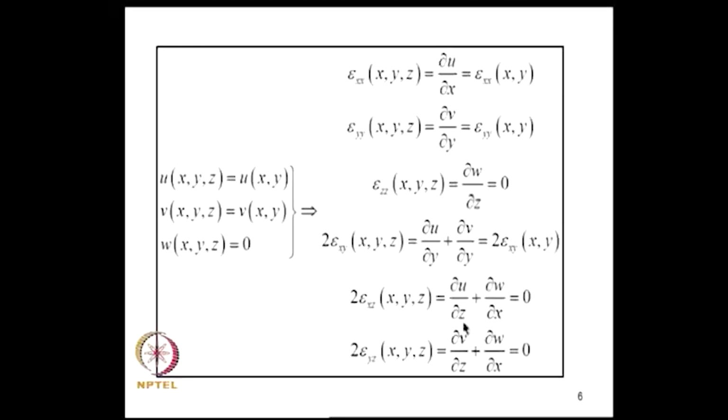So, this is the basic plane strain model, postulates of plane strain model. As you see here, the postulates are on displacements, whereas in plane stress model the postulates were on stresses. Now, starting with these displacements, the route will be from displacement we will use strain displacement relations and obtain strains, and from the known strains we will obtain stresses